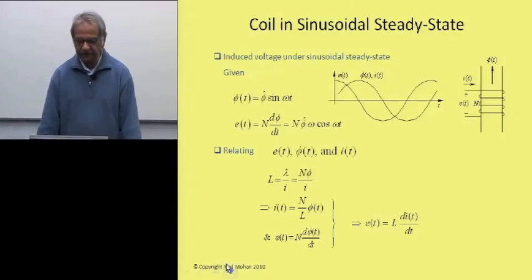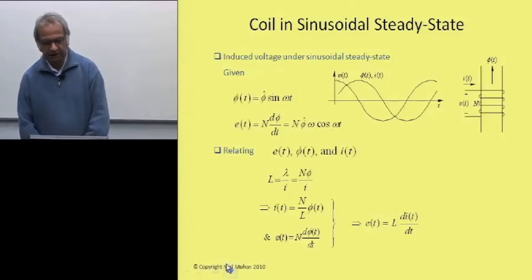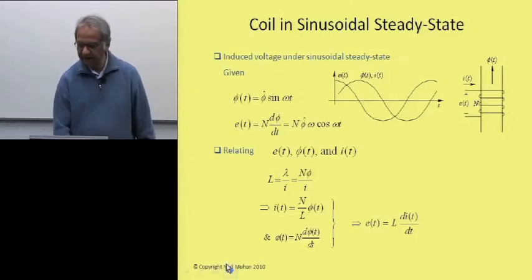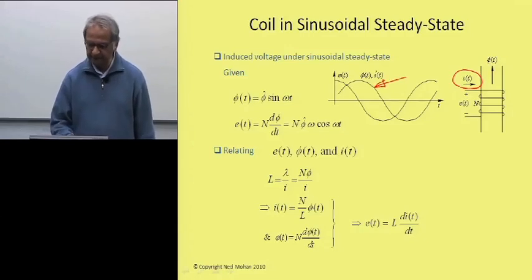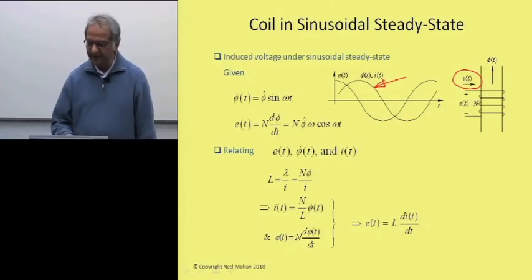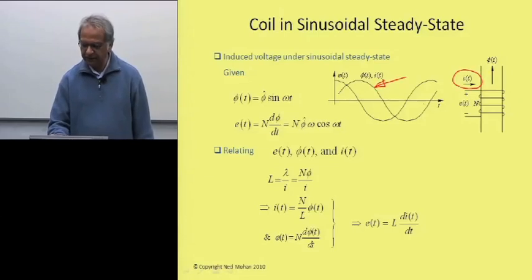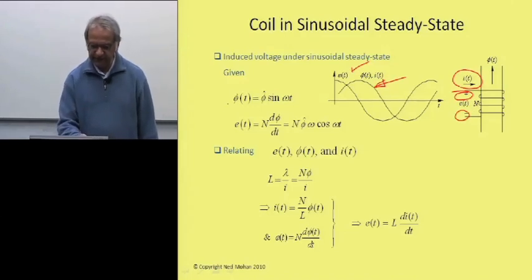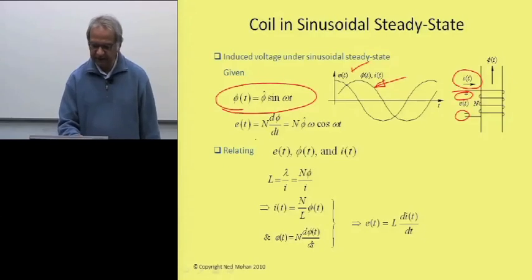So continuing this discussion of Faraday's law, if we have a current varying sinusoidally, as shown here, this flux here would also be varying sinusoidally. Flux and current are plotted to different scales. By Faraday's law, the induced voltage would be plotted over here and shown with this polarity. So you can see that if flux is varying sinusoidally, this voltage would be varying cosinusoidally.